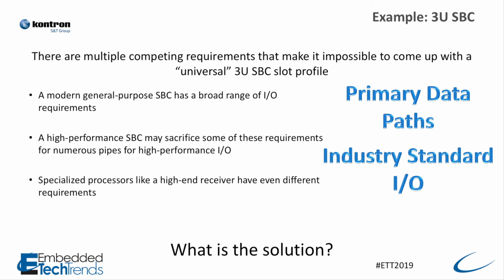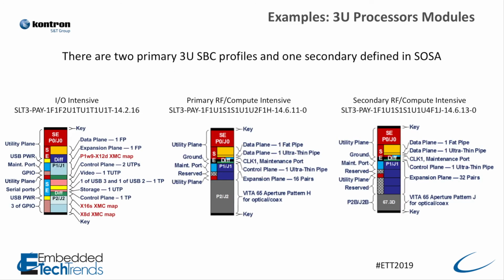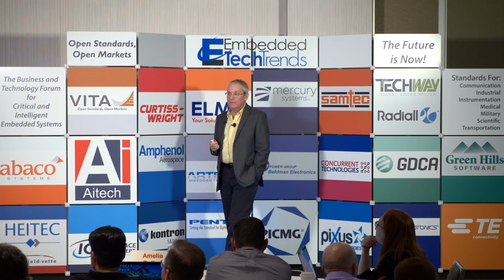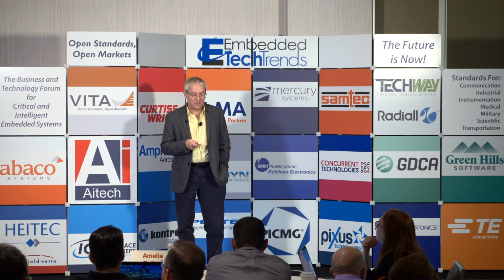So what's the solution? What we did is we defined two basic slot profiles. One is what we call I/O intensive, where it's focused on those general purpose types of signaling that you'd expect on an SBC. Basically bringing your common computer into an embedded environment. But one of the key things here also is the XMC mappings. We wanted to be able to support XMCs, so that's in here.